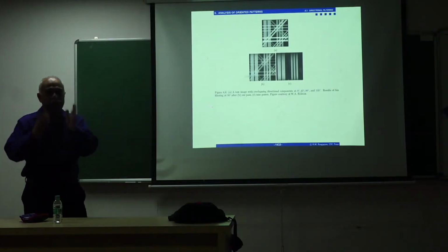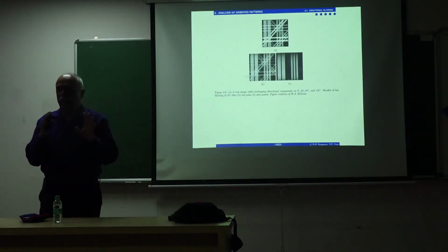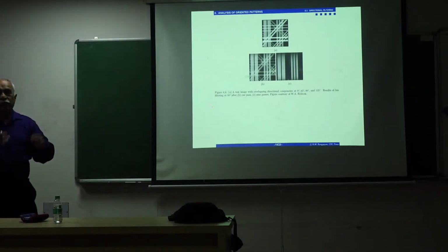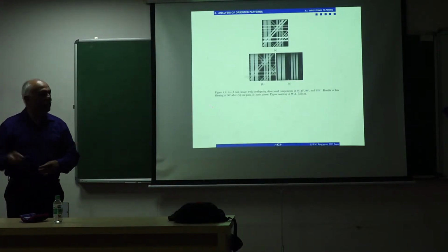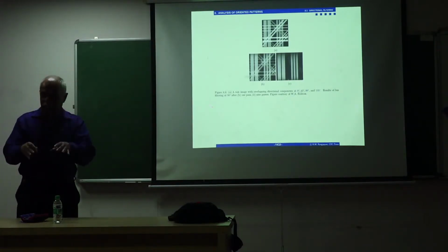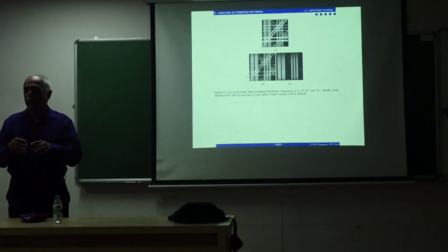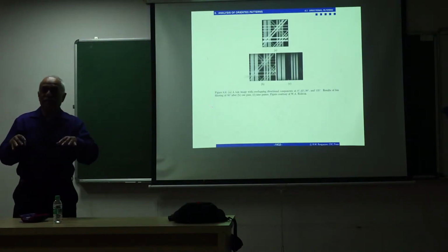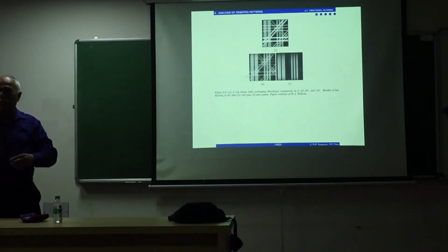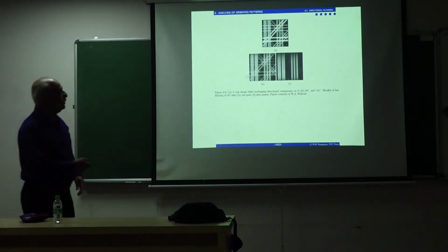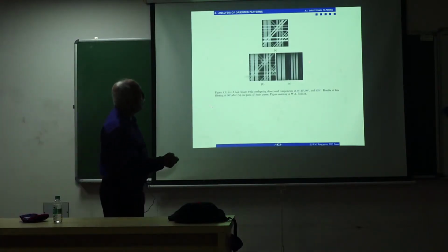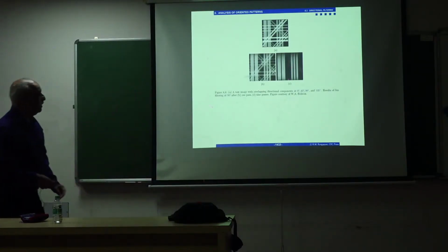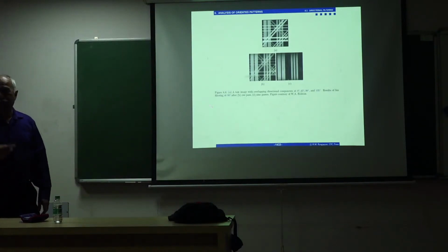Whereas if you take the Fourier transform and apply a filter, that is one shot. You can't do anything more. Whereas with these recursive filters, you can apply again and again. Repeated passage will suppress the undesired components. The gain will be multiplied over and over again, so the unwanted components are suppressed. There are still some artifacts you can see, but that's after 9 passes of the image through the filter.